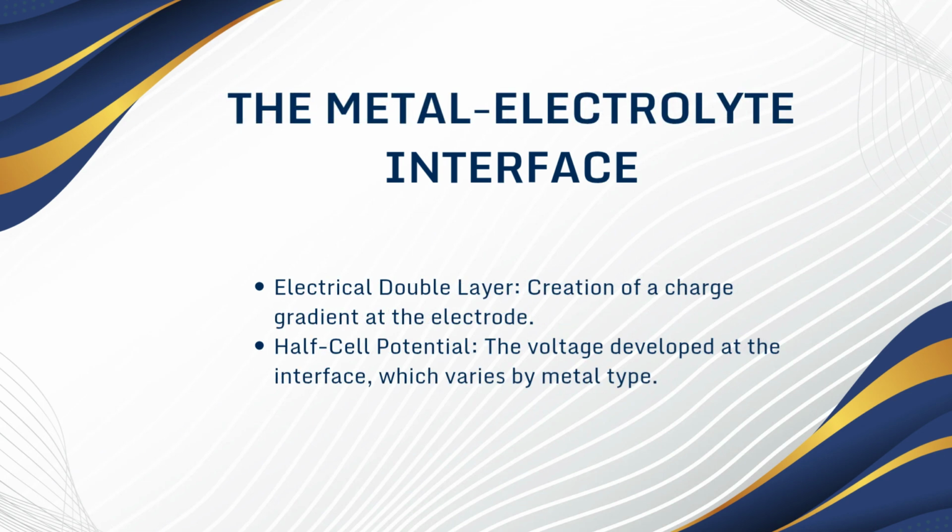When you put a metal electrode against the skin using a conductive gel, a chemical reaction occurs. A charged double layer forms at the interface. This creates a small voltage called the half-cell potential. If this potential is unstable, your medical reading will be full of noise.